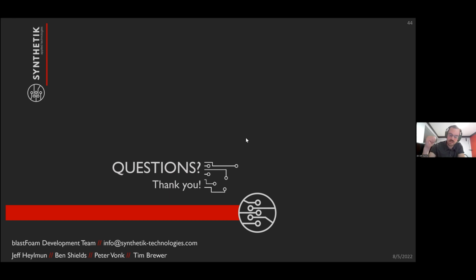So numerical discretization. We've done a little bit of work with it. We have all of the standard limited schemes from OpenFOAM, so limited Van Leer or linear Van Leer, Superbee, all of those. We typically use minmod or Van Leer.